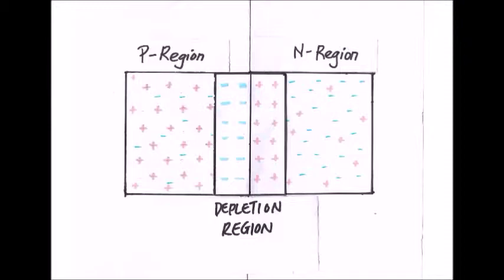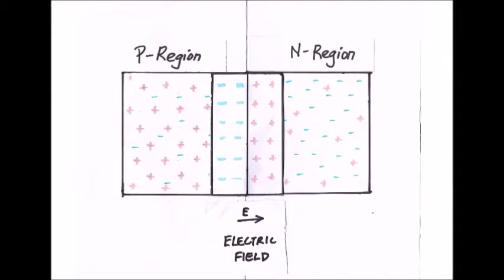The depletion region establishes equilibrium when electrons from the n region are repelled from the p region. In the depletion region, there are many positive and negative charges on opposite sides of the p-n junction. This causes a field of forces, called an electric field, to form. This electric field is a barrier to the free electrons in the n region, causing electrons to require more energy to move through the electric field.